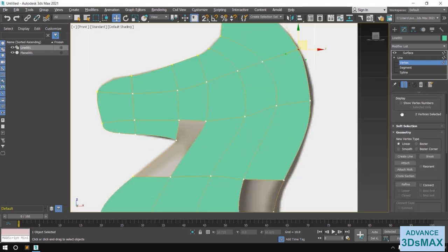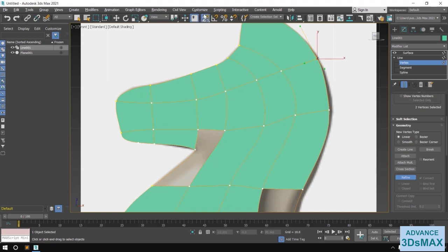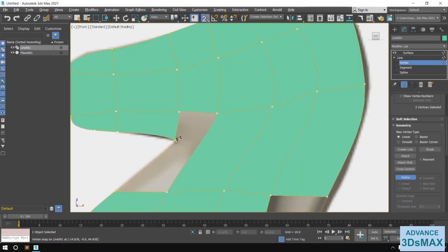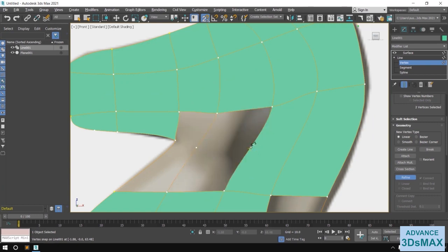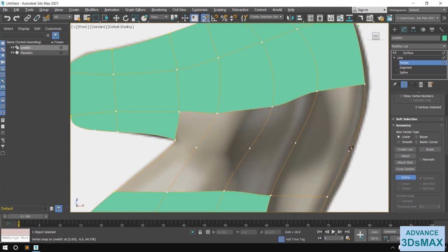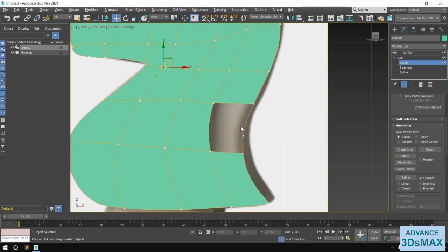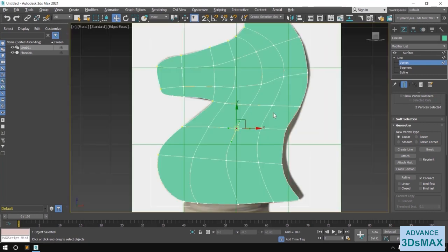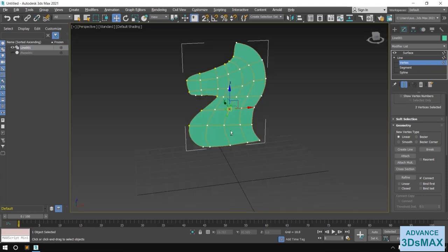Here I go to the refine tool and make sure its checkbox is selected, click on the snapping mode, connect only, and then release this tool with the right click. Same as here, I delete this extra point. Okay, surface creation is complete, but it looks flat.